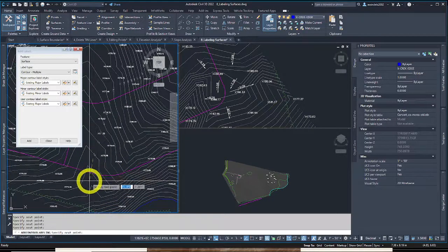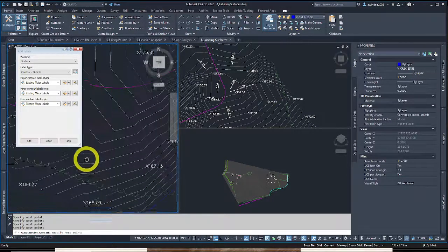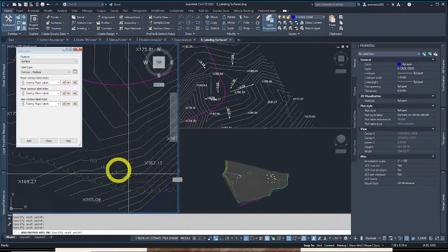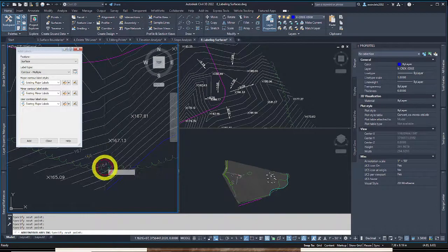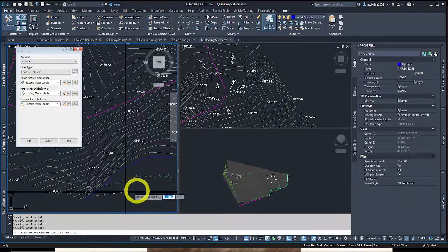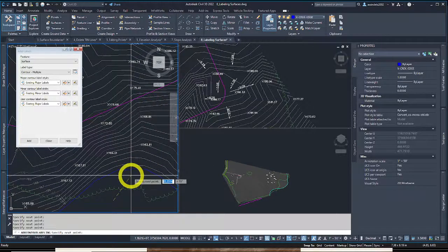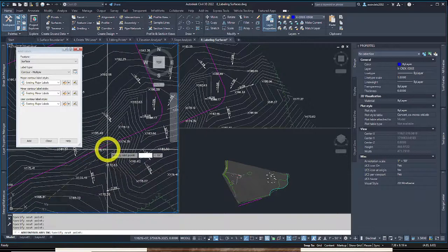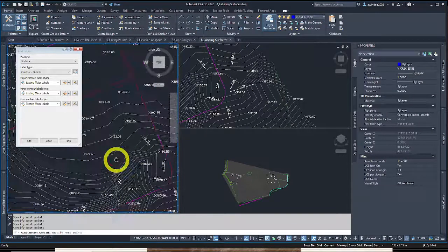So I'm just going to keep drawing my contour labels. It says the exact contour in integer, nearest foot. It's usually what contours are. We learn user-defined contours usually are to odd integers and fractions. I can always pick outside of the surface and continue on and move back onto it. So you can keep doing this.